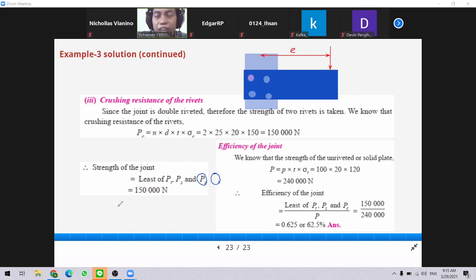If you have a very thick or very thin plate, it will be difficult to join by welding. Or if you have different parts, for example composite and aluminum, we cannot use a welding joint to combine these components, because they are not weldable.